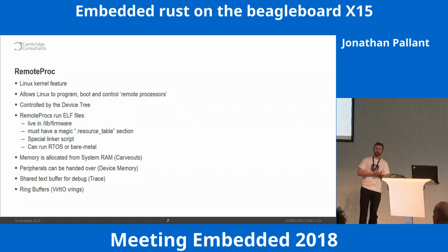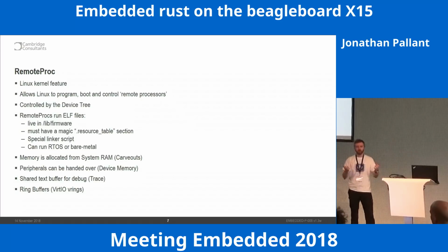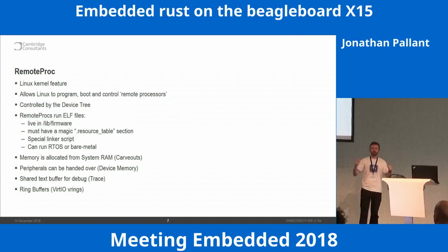If you've not seen the device tree, this was the kernel's answer to the problem that every single ARM board needed a custom kernel built for it. With a PC, there's a BIOS, and you can run some generic code that asks the BIOS, what hardware do I have? There's some mechanism to discover the hardware. With ARM systems, that doesn't exist. And so the kernel that ran on, you know, the Beagleboard would not run on a Raspberry Pi or would not run on something else. Well, the device tree is a generic way of saying, this is the tree of stuff in my system. I've got 4 UARTs, I've got 3 SPIs, they're at this address, load this driver. I've got a video processor, it's at this address, load this driver.